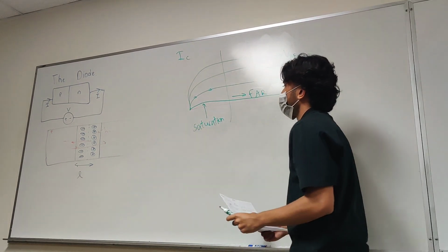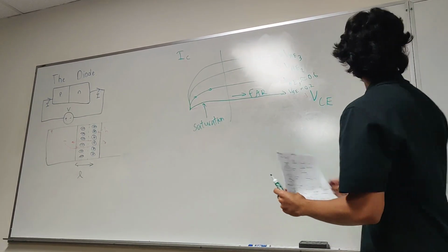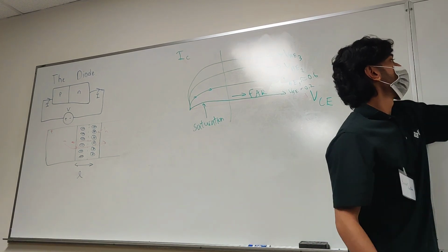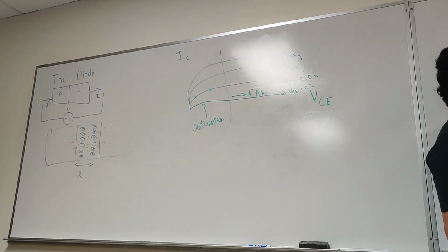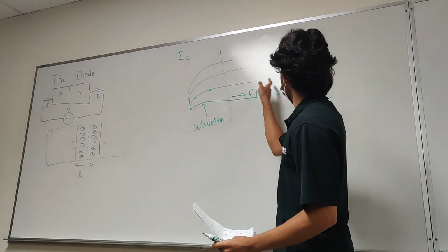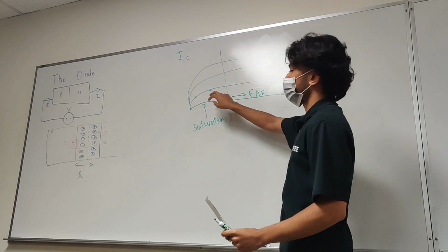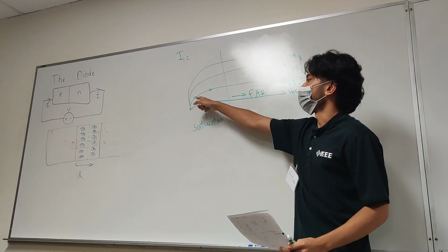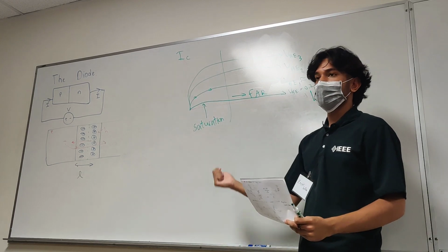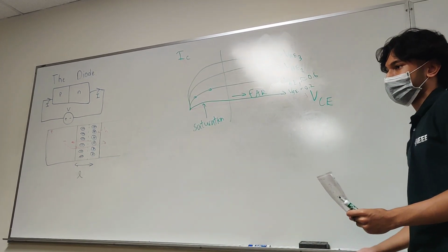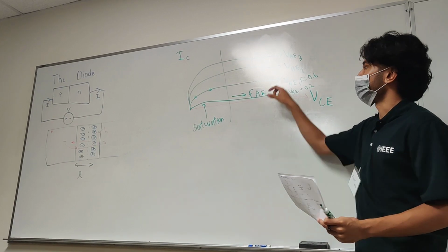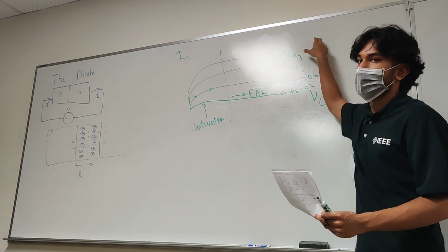And what this refers to is, our diode here, this is forward biased. That's great. We don't have enough voltage here to really do anything with it though. So, we have enough voltage. We're at 0.6, that's perfect. But VCE is too small. So we still have changes here. Okay, that's what we call saturation. This is in contrast to the MOSFET where saturation's good, BJTs, saturation's bad. We want to be here in our linear regime, forward active regime.